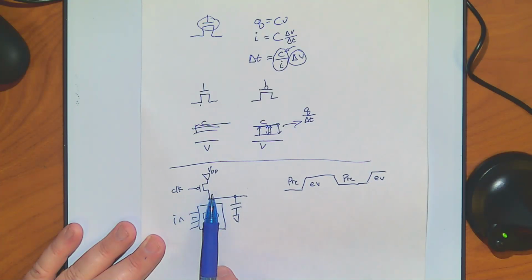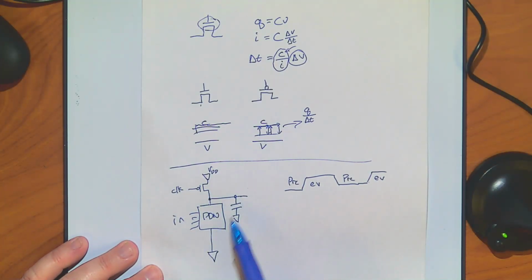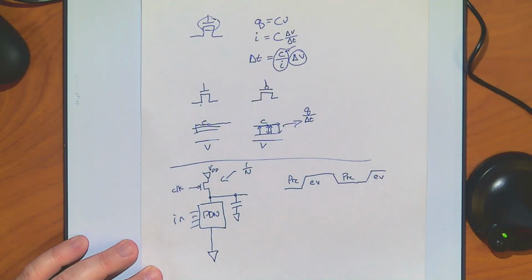Now, I took away N PMOS gates and I put one back in. So the relative size of this charging network compared to my original one, if there's N inputs, is 1/nth of what it was before. Right? Because you needed one transistor for each of your input lines. So this is just 1/n now.